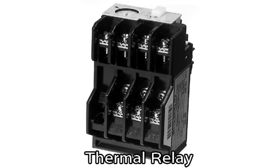The thermal relay is composed of a main circuit terminal with a built-in heater and bimetal and an auxiliary relay. It is used to intercept the circuit when the latter exceeds a certain limit. In the sequence circuit, it is possible to detect overcurrent using this auxiliary relay. The auxiliary relay will not return to its original state even if the excessive current is stopped. Therefore, it must be manually reset once the excessive current error has been resolved and safety has been confirmed.